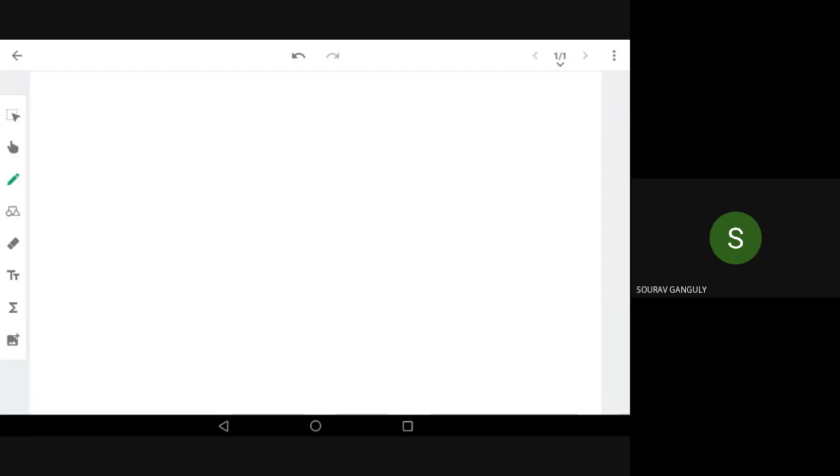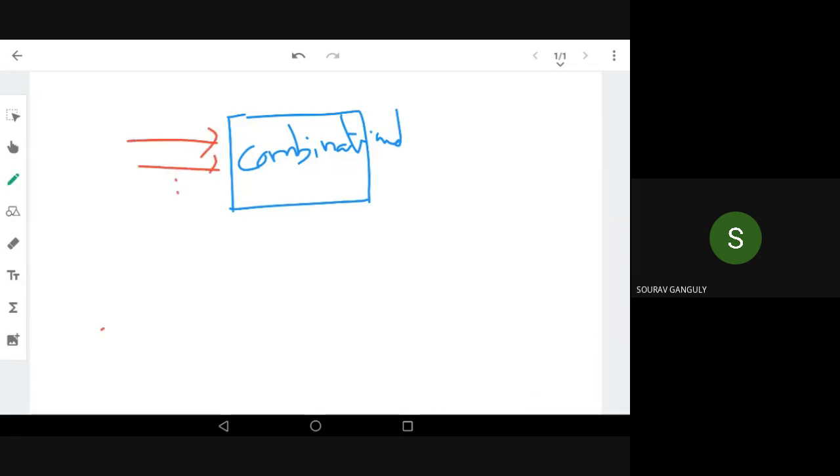So yesterday we discussed an overview of the basics of digital electronics. The main important thing in that is the big difference between sequential and combinational logic. I hope you got those concepts. This is combinational logic. What is the specialty of combinational logic? Combinational logic doesn't have any memory. That's the main thing. Whatever inputs you have, n number of inputs, you'll get outputs instantaneously based on the logical relationship between inputs, or the circuit or logic we have designed.